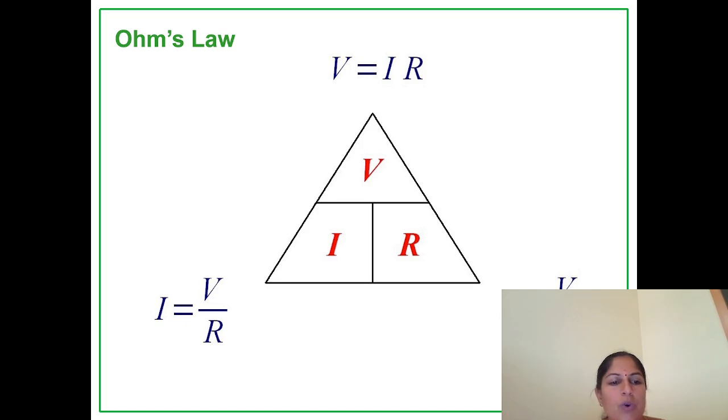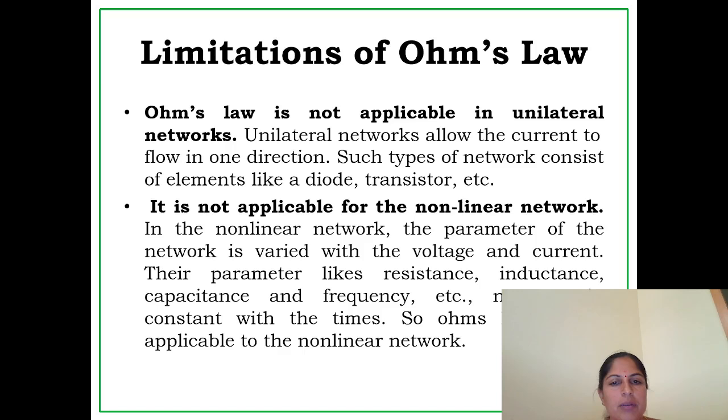So the voltage pushes the electrons, current is the flow of electrons, and resistance opposes the flow. The relationship between them is given by Ohm's law, V = I × R. The Ohm's law triangle is an easy memory tool to derive all three formulas quickly.